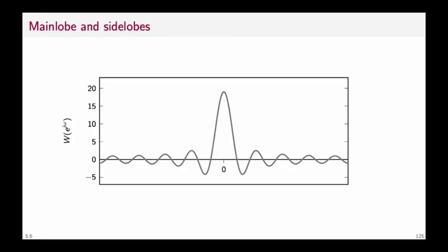The shape of the Fourier transform of the approximate filter will depend then on the shape of the Fourier transform of the indicator function. So if we look at it here, we see that we have what is called a main lobe, here in blue, that will determine how steeply the approximate filter will transition from the stop band to the pass band. The width of the main lobe is what determines the steepness, whereas the amplitude of the so-called side lobes will determine the amplitude of the error on either side of the transition band. And this is what determines the Gibbs phenomenon.